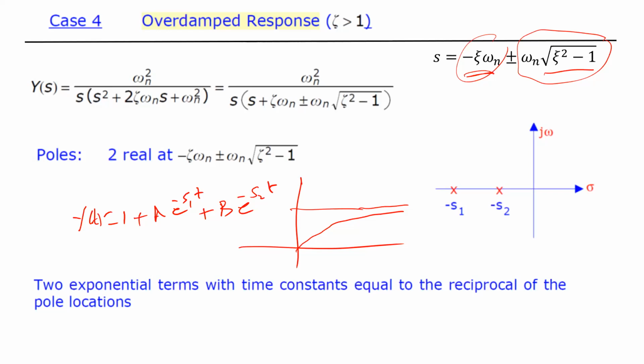As you said, zeta, the overshoot, the settling time, this is in terms of the parameters of a second order system. For higher order, we will approximate them if the roots are far away from those dominant ones. If not, yes, I agree with you, it will be difficult.